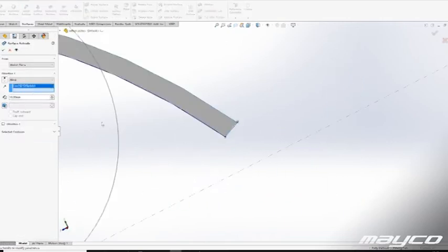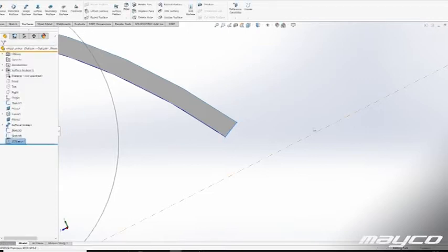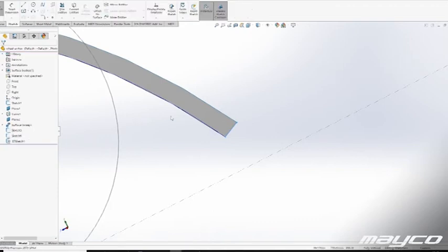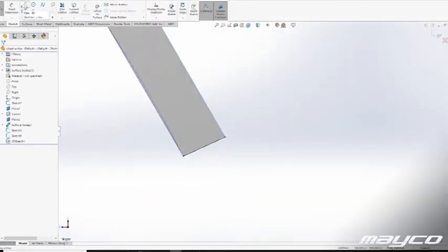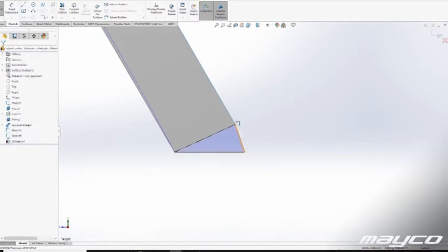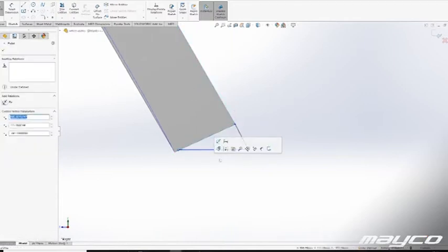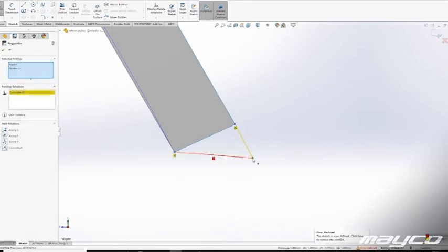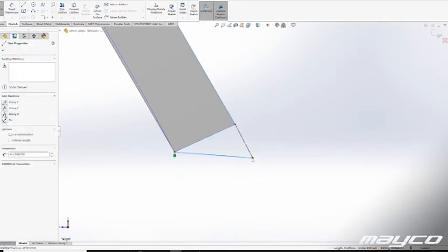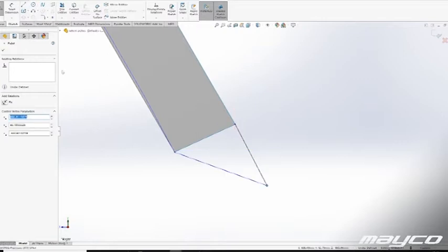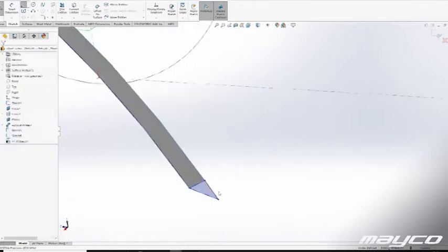And using that sketch and a surface loft, I generate the wheel arch, the straight part on the wheel arch, and this basically helps a fiberglass part to become very stiff and rigid, and also keeps the shape very well. And then we go over to the rest of the wheel arch, where we will have a nice curve and some bend.